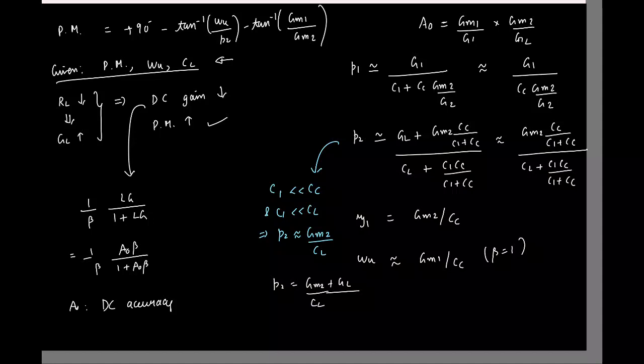I can increase GM1 or GM2, anything. Okay. So again, you can increase GM1, or let's say if you can't do it beyond some point, you go ahead and increase GM2. And again, to increase it, you will have to increase the current and width simultaneously.